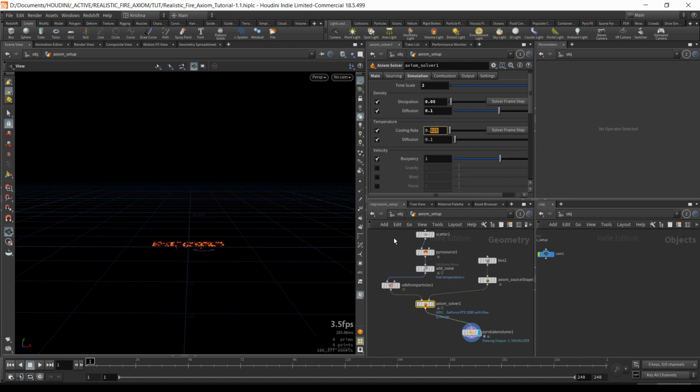All right, so cooling rate is very important. Because this is a fire, I don't want it to last too long. So I'm going to bring the cooling rate to 0.2. Again, you can adjust these parameters and try it out yourself. But cooling rate basically cools down the temperature, how quickly the temperature will cool down per timestamp. That's what that is.